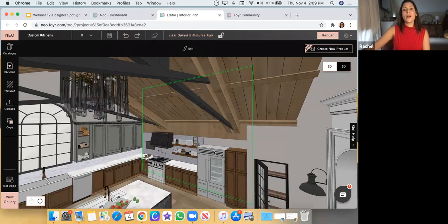Let's see. Can you change the grout color of the backsplash texture? So right now, no. What you would have to do is find a picture of the tile that you want with the grout that you want and upload that as a custom texture. Do you know how to upload a custom texture? Brandy, you do. Okay. One of the caveats is you'd have to just find it online. It can even be a picture. Try and make sure that the lighting is as even as possible on the snapshot that you have, because that can really affect the overall look when you're increasing the number of tiles. If this side is well lit and this side is shaded, that gets a little wonky. But that's a good future feature that we should definitely have, changing grout specifically.